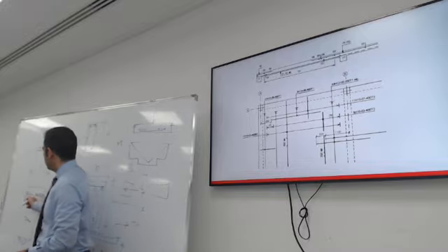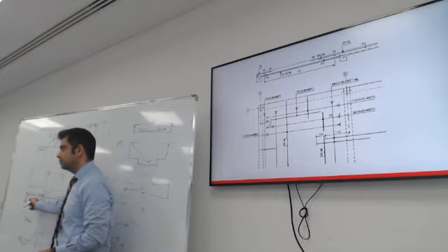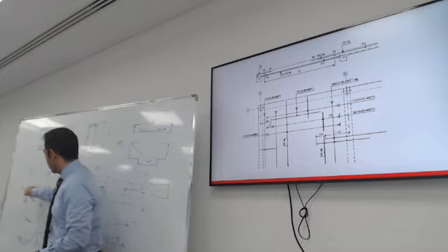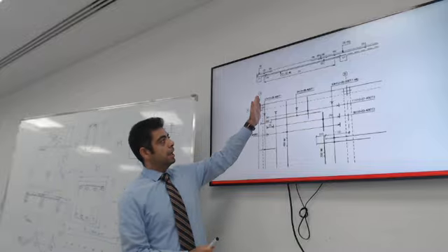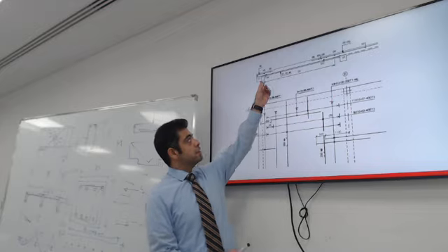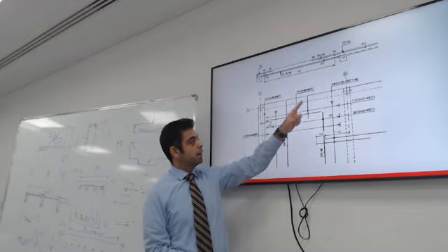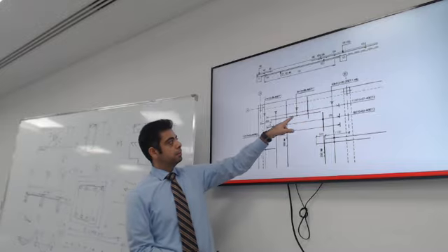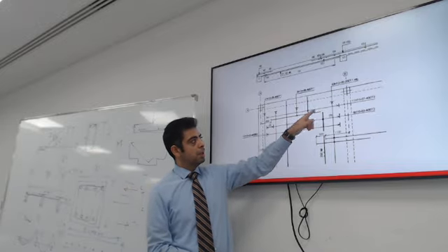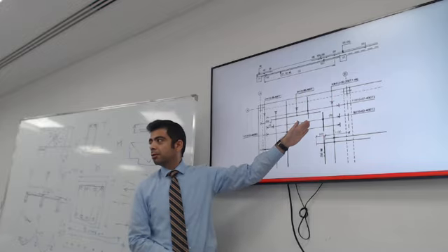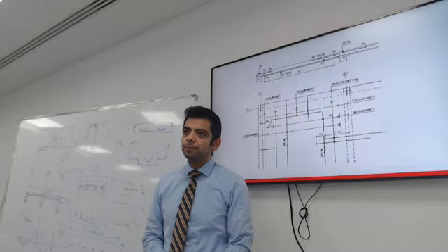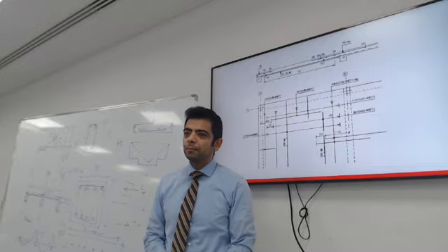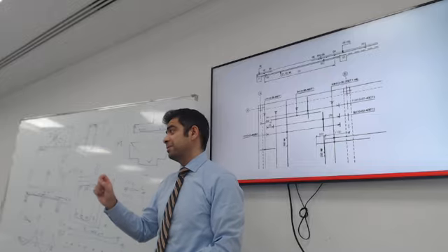So the main reinforcement is bottom. What are these opposite direction bars doing? So this is grid line A, this is grid line B. This horizontal bottom bar is this line. There is another bar perpendicular to it. What is this bar? This is a very important concept.